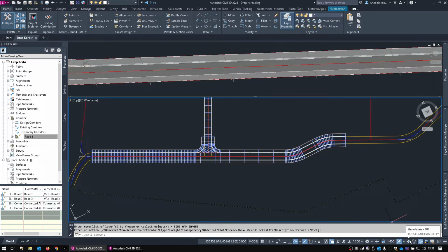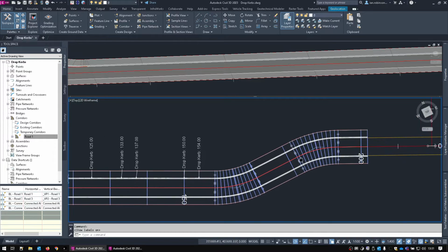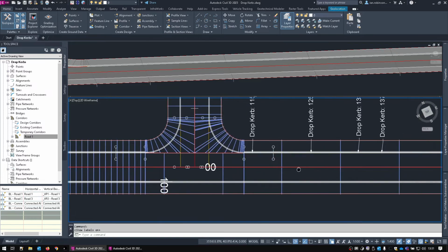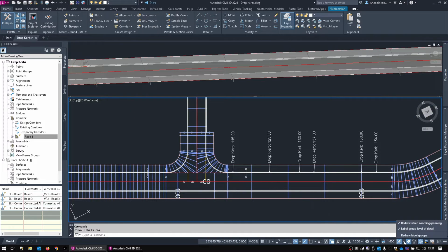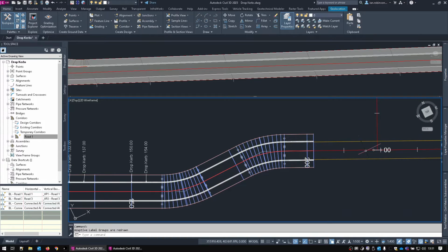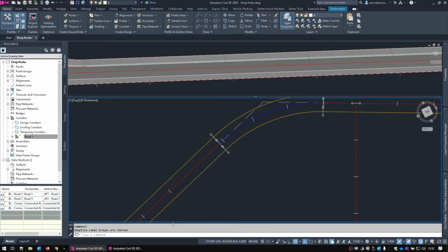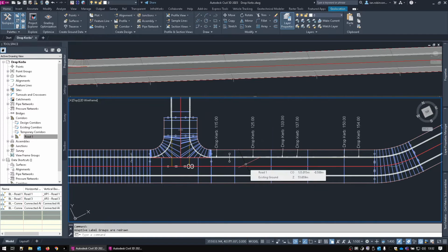And we can turn our labels on. Oh, this is a new feature. I'm not turning this into a new feature video, but just be aware, we can turn labels on and off now. If you've got performance issues, turn all your labels off. It'll make a massive difference. There's also this tool here, which is the Optimize tool. If they're all turned on, for example, none of the labels are being drawn that are off the screen. So if I pan, you'll see they will not appear. They are appearing though. Why is that? Oh, go in here and redraw them. Redraw label groups and then pan across, and you can see there are no labels now. So the labels don't appear until you finish your panning. Pan around, let go, and then the labels will appear. There they are. You can see them appearing as we go. So again, it's all about performance. It's just a nice little tool in here.